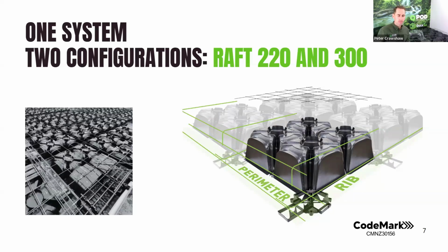That built-in bar chair is a patented design of QPODs, which puts that mesh right where it needs to be. Some of the other systems out there don't actually put the mesh right in the middle of that topping, which is concerning for designers of foundations. So 85 is the minimum. You can obviously extend that up wherever you like. When you're starting to get anything above, say, 120 or 130 millimeters of topping, you might start needing to prop that mesh up a little higher in reality.